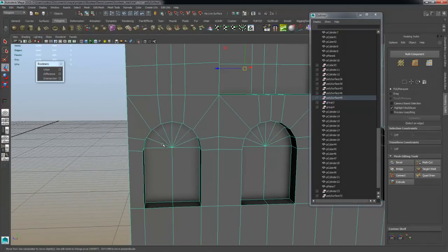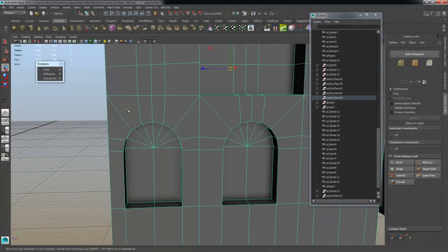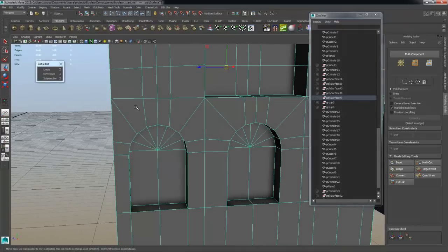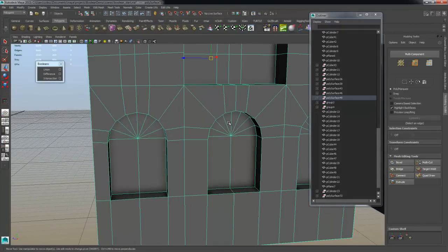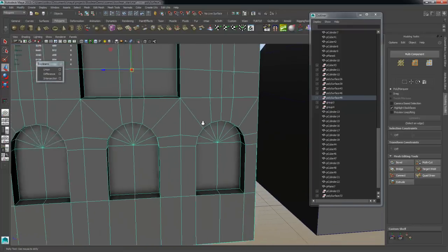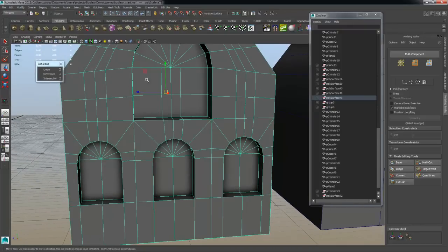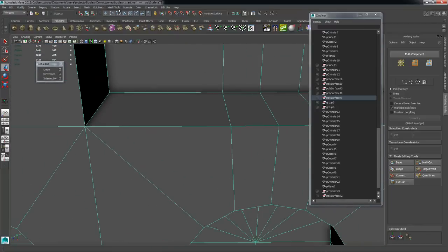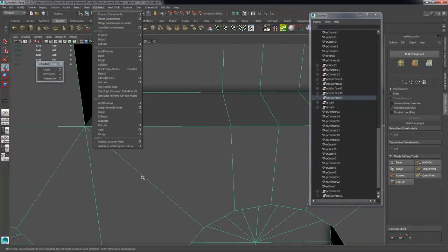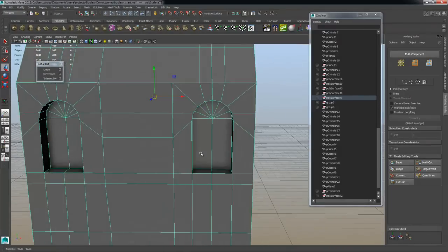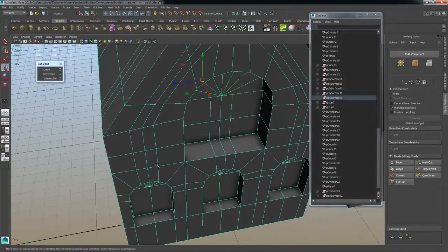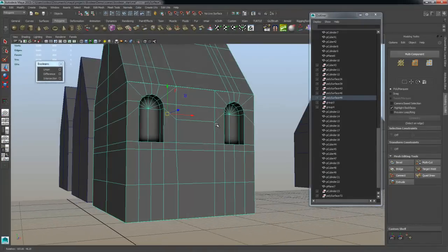And I've done another extrude outwards, and I've straightened the edges on the sides, and that allowed me to then make a cube or some sort of rectangle shape out of it, that I can then snap to the next and the next and the next, and finally combine everything, and then do vertex weld or component merge, and that's going to collapse everything to one single point. And that's how I got to this result.